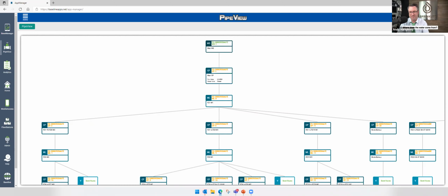And really ask the question, it comes from this source over here. Well, okay, is there another source above that? Like, we really want to know where the water comes from originally. Yeah. And we know that we're seeing more and more projects where you've got a primary source and then a secondary source. And that primary source may be a water cistern or a surface water, groundwater that you're pumping from, or it may be a municipal connection, right? So understanding where the water's coming from is important in setting up the configuration of that hydraulic structure.